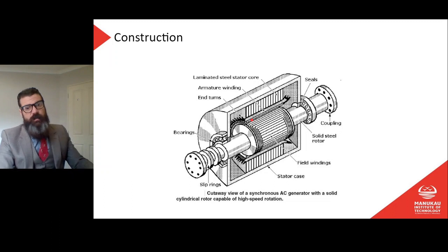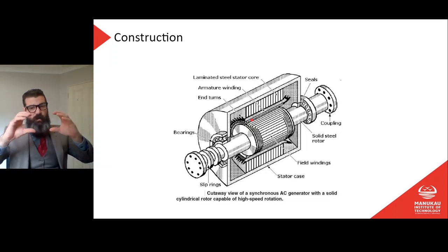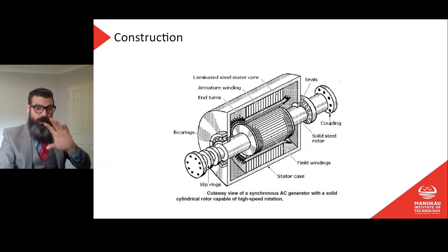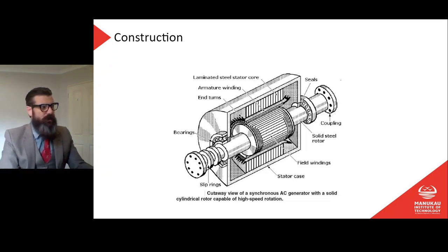magnetic field. So in this situation, the magnetic field is not stationary with the conductors moving inside it. We actually have the magnetic field turning and the conductors remain stationary on the outside. It's the same though, we're still going to have the conductors cutting that magnetic field.